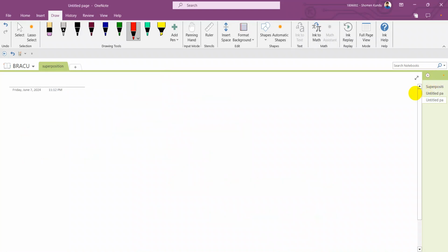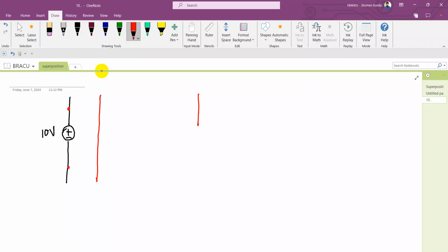One important thing is how to turn off a current source or voltage source. There are two different techniques for turning them off. First I will show you how to turn off any current source or voltage source. Suppose this is a voltage source, you need to short it out to turn it off. And suppose you have a current source, you can turn off this current source by open circuit. Okay.